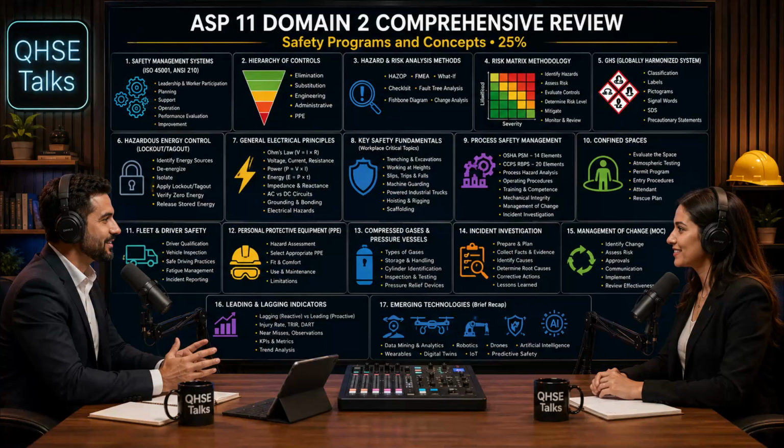Perfect. So we have 80,000 pounds of force multiplied by an unknown distance equals 400,000. We just divide. 400,000 divided by 80,000. The zeros cancel out, leaving us with 40 divided by 8, which is 5. The answer is 5 feet. The 40-ton counterweight must be mechanically positioned exactly 5 feet away from the center mast on the short boom to balance the 10,000-pound load sitting 40 feet out.